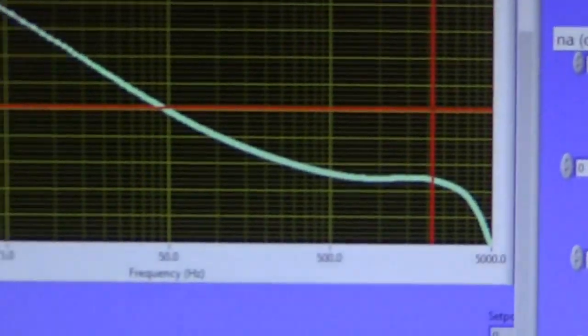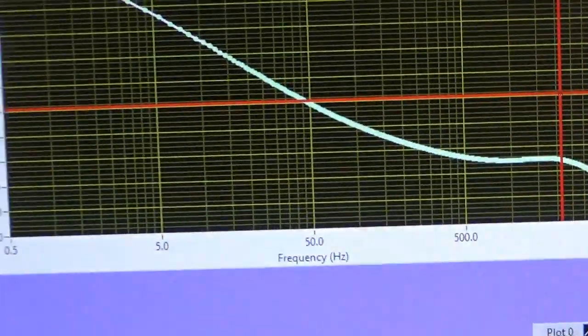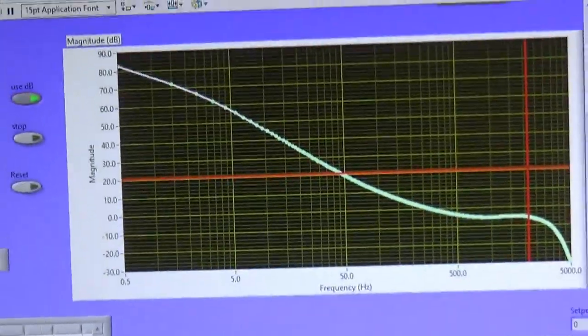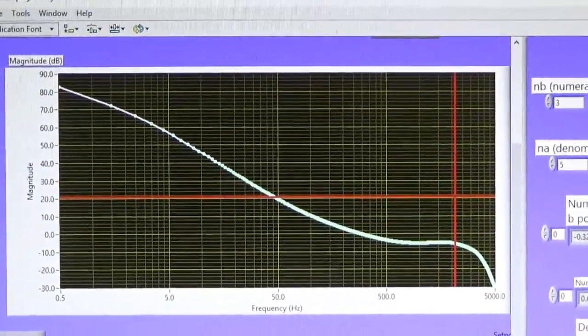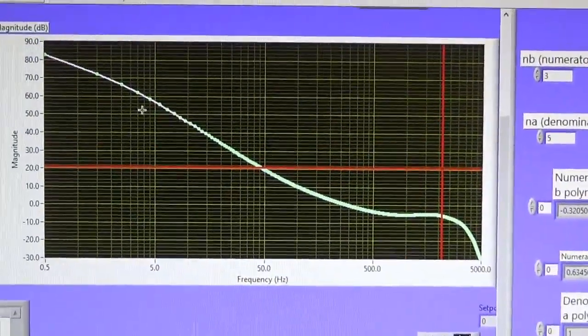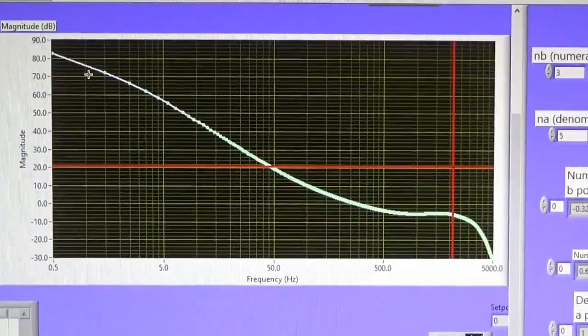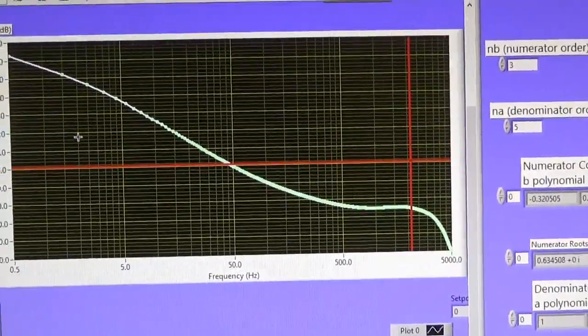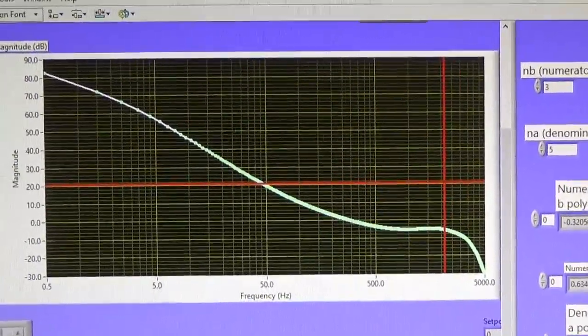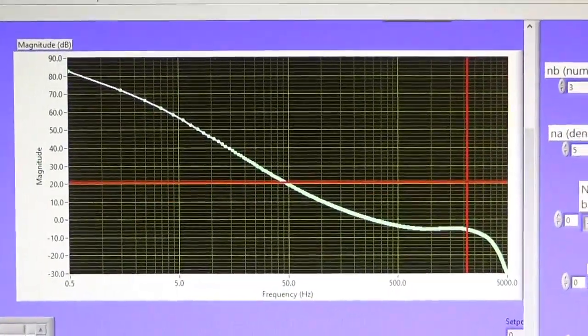you may be interested. If you don't put the integrator in, if you haven't got a proper model, then you've got a model just from this point of view of speed. Let's have a look and see what happens when you do that. Of course, we won't get our integrator here. We won't get a -20, -40. We'll just have a flat, or something nearly flat, and then it'll go down because it'll be first order plus the thing.